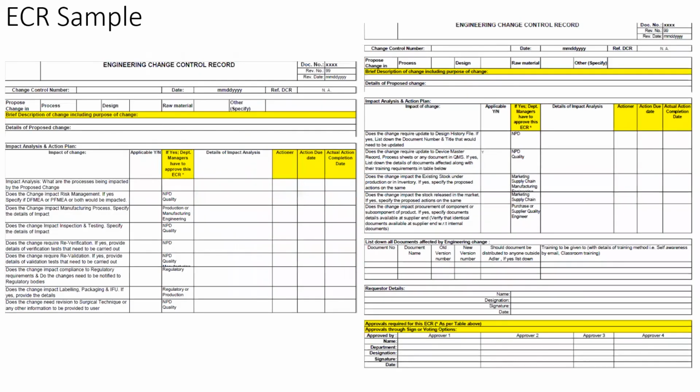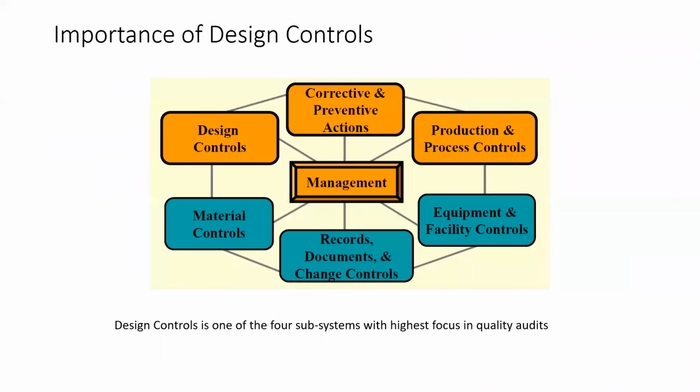So it is very important to define an engineering change control procedure once a design is released to market, where every single stakeholder, department, or function, design, quality, regulatory, manufacturing, supplier, all the stakeholders who are contributing to the realization or the manufacturing of that product have to study and opine on what else will be affected if this is changed. Without having that process very clearly defined, one is not allowed to change anything.